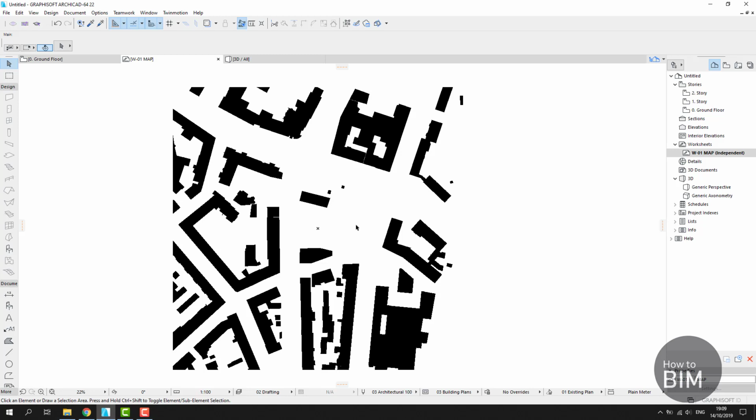The measure tool is something that you can find up here on the taskbar, but you can also use one of the most commonly used keyboard shortcuts, M, that turns on this measure tool. If you want to go back to the selection tool, just press M again and it will change back to your previous tool. So turn this tool on and off just by pressing M.